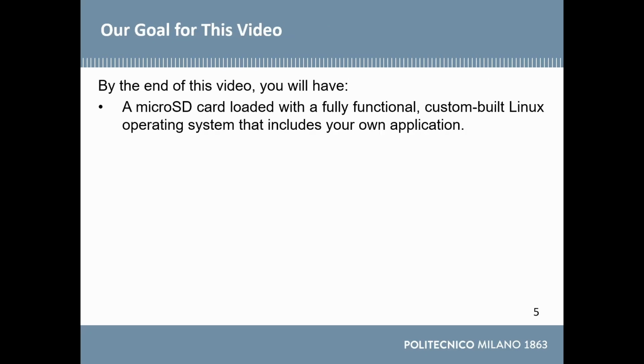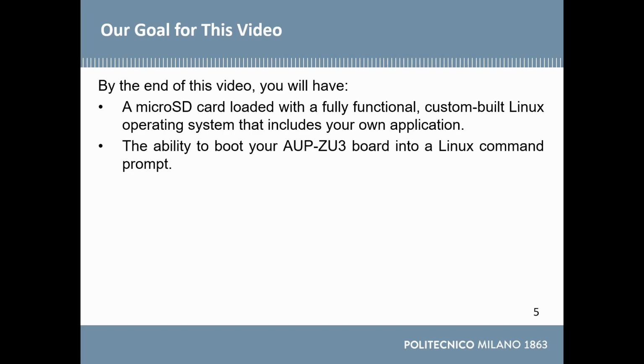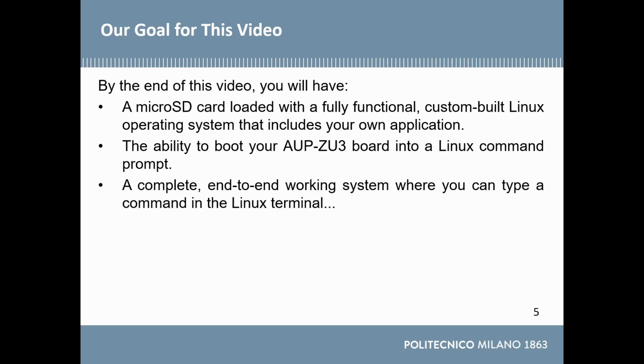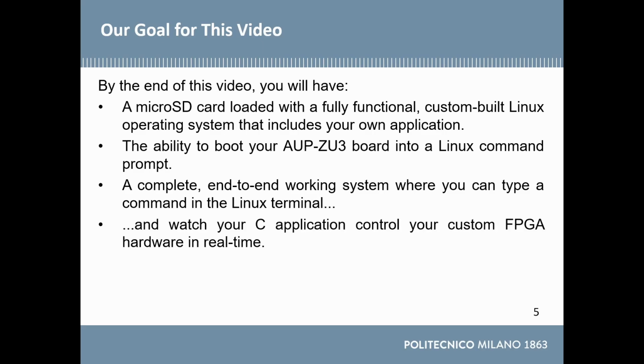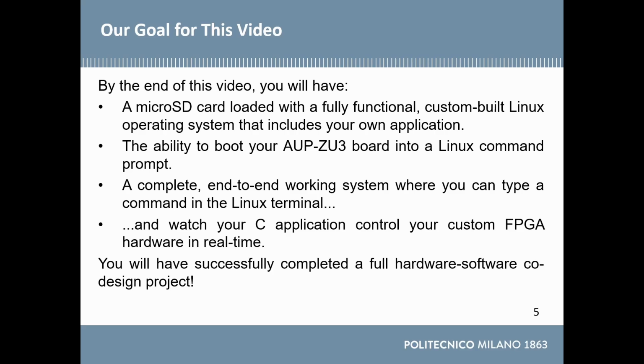By the end of this video, you'll have a micro SD card loaded with a fully functional custom-built Linux operating system that includes your own application. You'll be able to boot your AUP-ZU3 board into a Linux command prompt. You'll have a complete end-to-end working system where you can type a command in the Linux terminal and watch your C application control your custom FPGA hardware in real time. In the end, you'll have successfully completed a full hardware software co-design project.